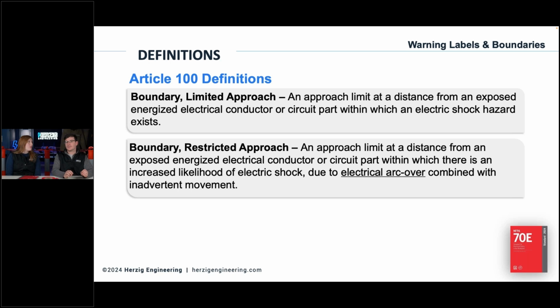Right. So there's a lot of things that could cause someone to get involved in an electrical circuit that is above and beyond what you might be thinking of. So using improper tools, obviously you can get shocked from that. Yes. But within the limited approach, that 42 inches, that 3.5 feet, it is possible, even at that point, to cause someone to get shocked.